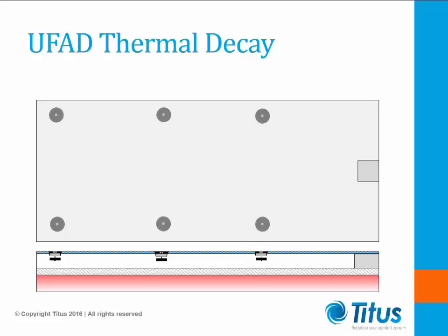Typical overhead systems are fixed, and retrofitting them, especially to accommodate drastic layout changes, can be very costly. Underfloor systems have the advantage of easily changing the layout. With an open plenum design, reconfiguration of office layouts is simple. But if zone control is desired, the plenum can be partitioned into smaller zones.